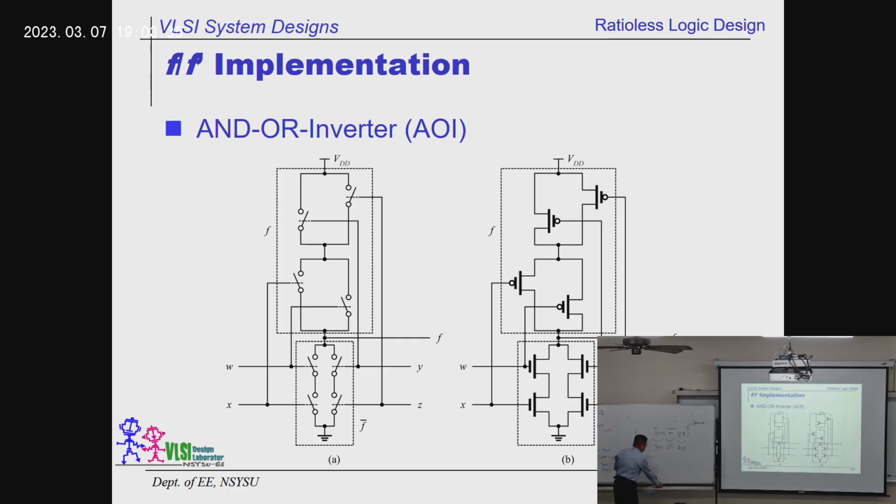So then the next thing you want to ask is how to tune the size. It's almost the same. Okay, in the bottom you see that we have two transistors. They are stacked together. So the original is W. Here you got to have 2W over here. 2W. Because they are parallel, we don't care. Parallel is good. They are not going to cause any trouble.